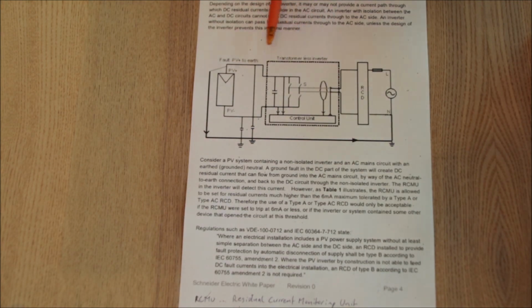A transformerless inverter is taking the DC from the PV input, switching it through a lot of electronics and filters, and passing this out as an AC output. But nowhere in between is there a galvanic separation, which would be there if there is a transformer built into this unit. If you are talking about transformerless inverters, so every grid-tied, grid-interactive inverter nowadays would almost certainly be a transformerless one.